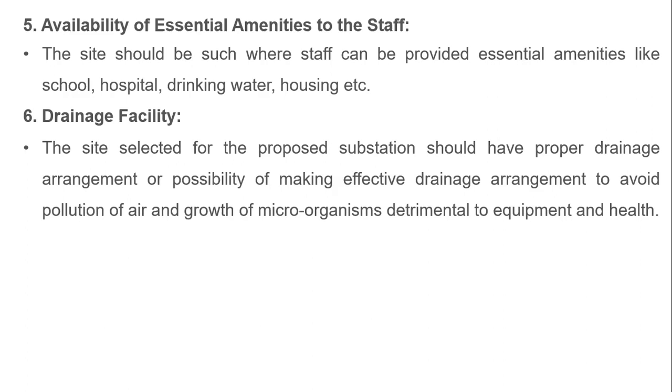Next topic is the rating of distribution substations. How will we decide the ratings of distribution substations? The rating of a distribution substation depends upon the load density of the service area. In that service area, how much load there is and what the load density is in the particular area will be calculated, depending upon the rating of the distribution systems.